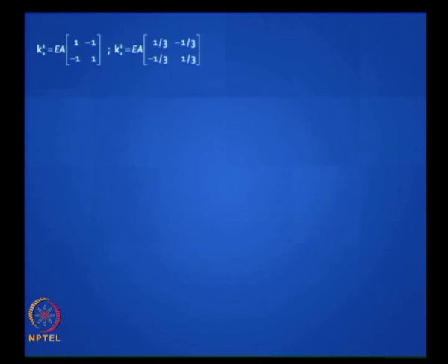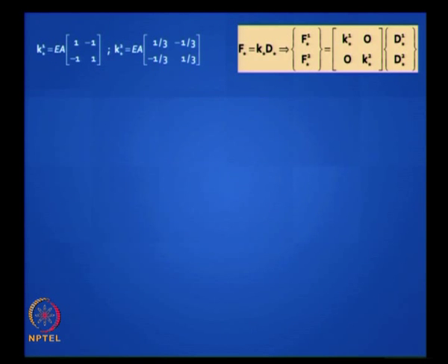Next step, you write down your element stiffness matrices. This is just the same way we did last time. Can you generate the structure stiffness matrix by the TD formulation? What should you do next? If you want to put it all together and have the unassembled matrix, whatever you got here, K1 star, you should put here, whatever you got here as K2 star goes here. Remember, it is a diagonal matrix, they are uncoupled. How do you use this matrix to generate your final answer?